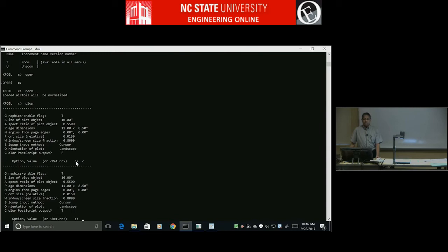white, because later on we'll see this when we do polar files. You'll have lots of lines comparing different airfoils. Let's say you're comparing 3 airfoils and you're plotting the drag polar. You'll have 3 lines, and if one of those is yellow, it'll just almost be invisible. But if you keep black and white, Xfoil automatically gives different line types, and it's actually pretty clear. So just because there is color, don't go and use it.